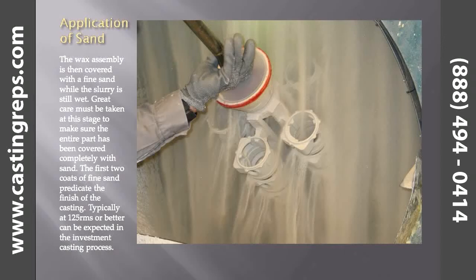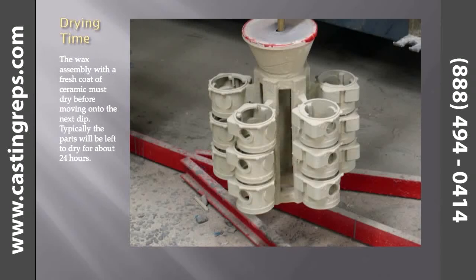The first 2 coats of fine sand predicate the finish of the casting. Typically, a 125 RMS or better can be expected in the investment casting process. Drying time. The wax assembly with a fresh coat of ceramic must dry before moving on to the next dip. Typically, the parts will be left to dry for about 24 hours.